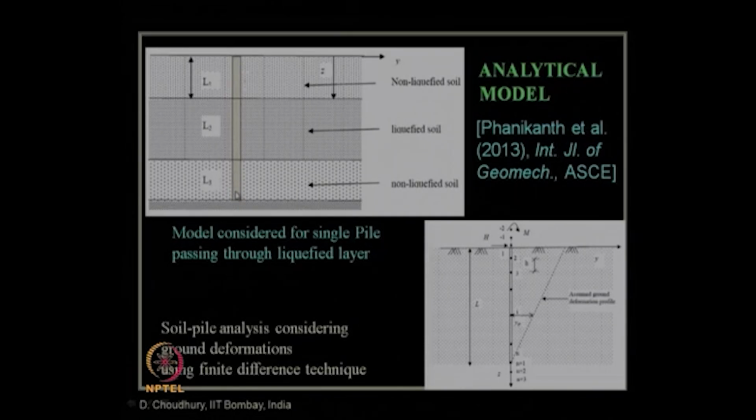So, that depth of L2, the parametric variation of this L2 over the entire length L of the pile, has been done in our analysis for various soil sites at Mumbai, using the local soil condition and different input seismic accelerations, to see how this analysis is obtained for the single pile foundation design in terms of bending moment and deflection. As we know, basic design parameters for pile foundation, we should get the bending moment profile along the depth, also the deflection profile of the pile along the depth, right.